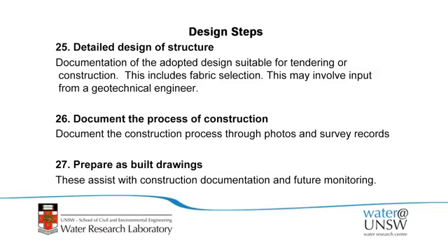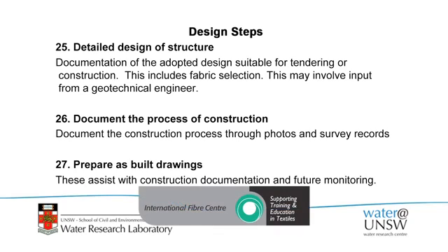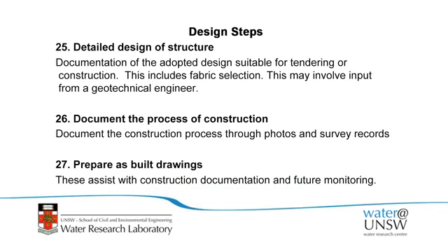And coastal engineers generally, the coastal engineering is all about the stability of the containers, but the stability of the wall itself in a saturated sand environment may require input from a geotechnical engineer as well. Document the process, assuming that's all happened and you've commenced building your structure. Document the process of construction through photos and survey records.